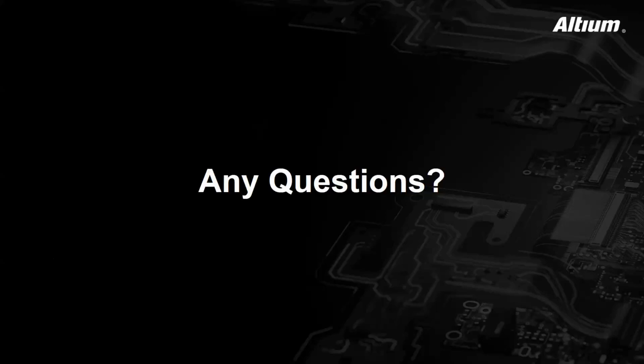To summarize today's session, we have covered primarily the ActiveBOM, and also showed how we can pull the real-time data inside Altium by using the ActiveBOM, which includes the manufacturer parts search panel, and also showcased how you can update the components to the latest revision if you pull the components from the cloud. I hope this webinar will help you overcome the challenges nowadays in your design phase.